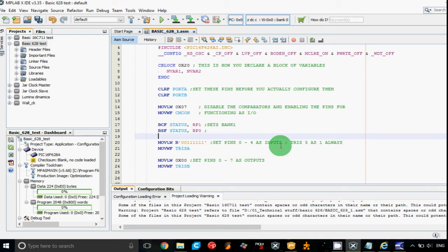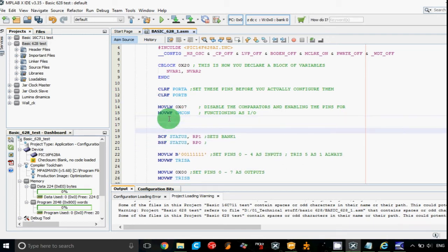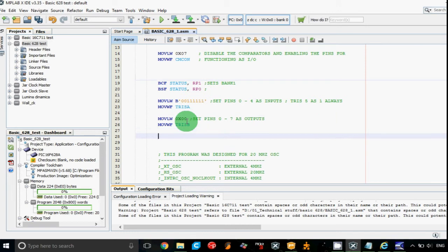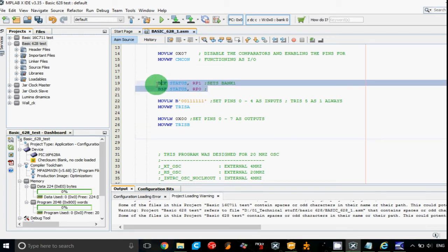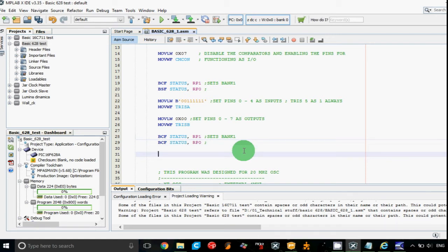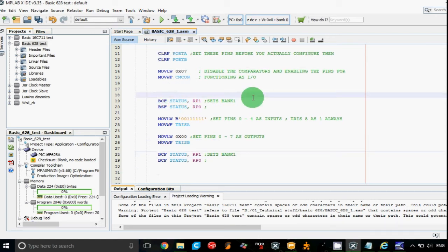Before I change these 3 registers, I need to set a different bank of memory, and after I set the 3 registers I have to go back to the initial bank of memory. So I'm gonna almost write the same thing, but I'm just gonna return the state of these bits in the register. I'm just gonna copy paste it. So instead of setting this bit, I'm gonna clear it now, and with this command right here I'm actually returning to the same page of memory.